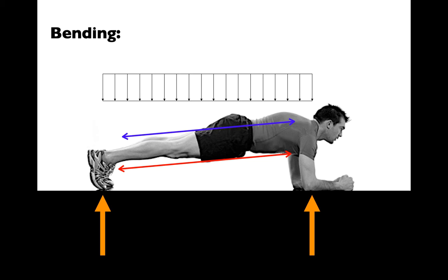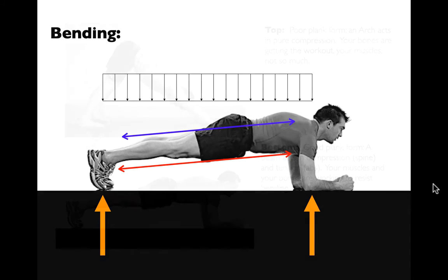And because, whether you know it or not, you're a simply supported beam in this configuration, you will have compression on the top, tension on the bottom. We'll talk about why this is a little more in the next set of lectures, but for the moment, know that when a beam is experiencing bending, in most simple conditions, the compression is on the top, tension is on the bottom.